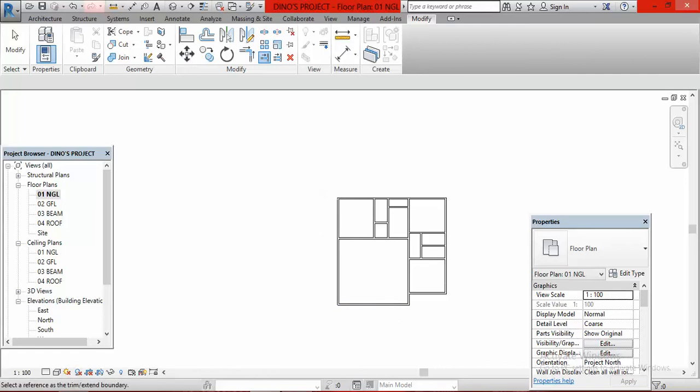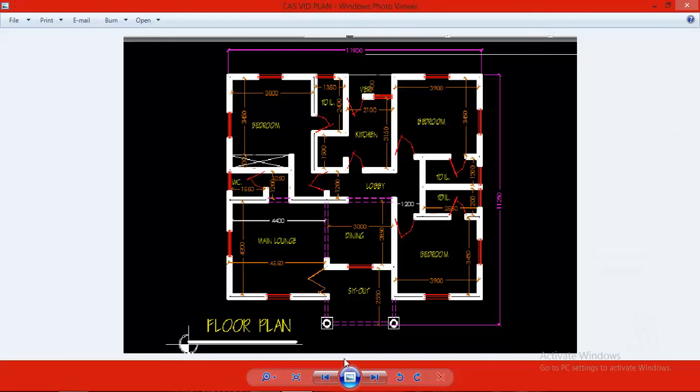What is the width of that Porsche? The width of that Porsche is supposed to be 3000 millimeters, which is 3 meters. Okay, 3000. Can you see it here? This 3 meters is the same thing with here, because they are in the same alignment. You can see this vertical wall and this vertical wall. So what you have on this sit out is what you have on the dining. So we're going to remove this sit out now. We are going to use this dimension. So 3000 millimeters plus 150 will give you 3150.